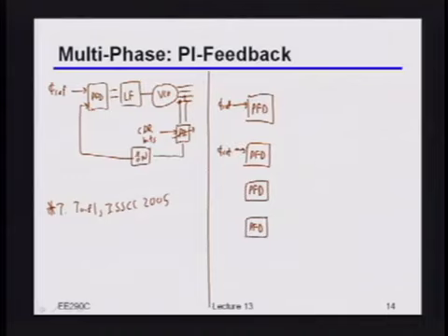That I'm not going to change. But now what I can do is, if I actually have 4 phases feeding back from the VCO, I could feed each one of those phases independently into each one of those phase detectors, right? So let's say I had a 0-degree clock, a 90-degree clock, a 180-degree clock, and a 270-degree clock.